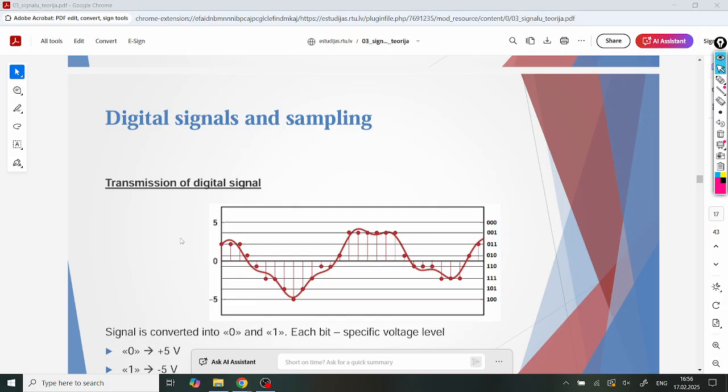Yes, so let's say now when we want to send this in a digital form in the modern world, we convert it into digital form, then we use optical fiber, which still, over such long distance, will require some regenerators to be used, but anyway, we'll see the effect. As we discussed previously, the conversion of analog to digital happens in two steps. First, you do sampling. Your red colored line is your original signal, which you sample and take readings from.